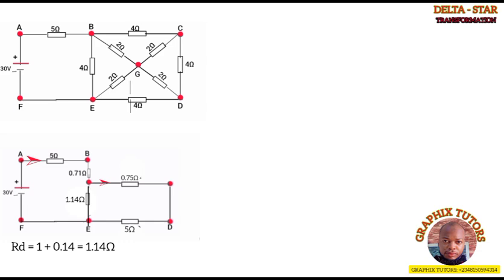Now if you look closely, this is what we're having. You discover that the current that flows through the 0.75 will continue flowing and come through the 5 ohm resistor, making 0.75 and 5 ohm to be in series. So if they're in series, you add them, making this become 5.75. We're having 5.75, we're having 1.14 and 0.71. These are my points B, E, F, and A.